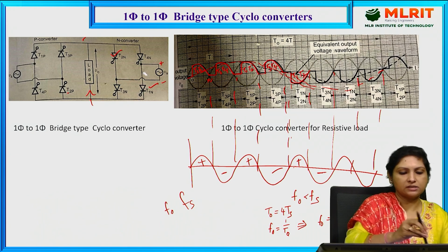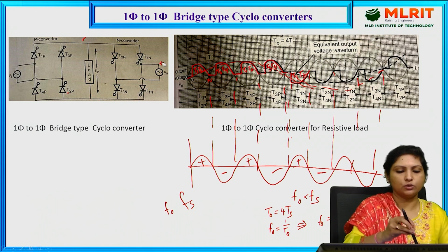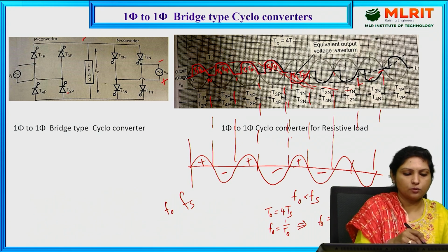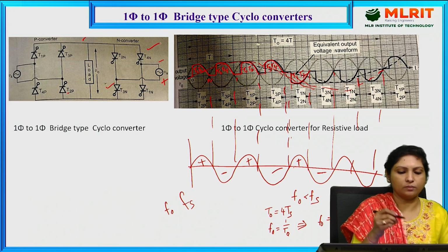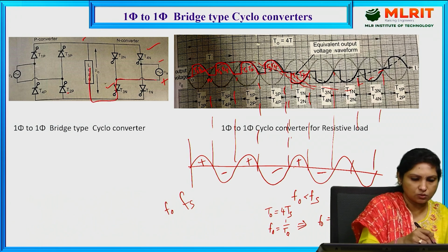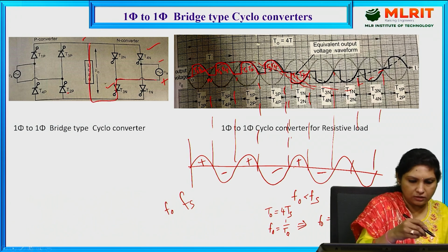During the negative half cycle, the polarities again transform into negative and positive, and because of these polarities, T3 will be forward biased as well as T4. So T3 is conducting current through the load, and then T4 and back to supply.